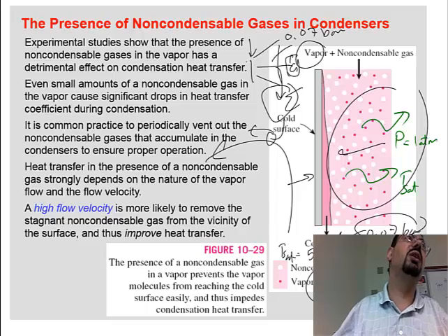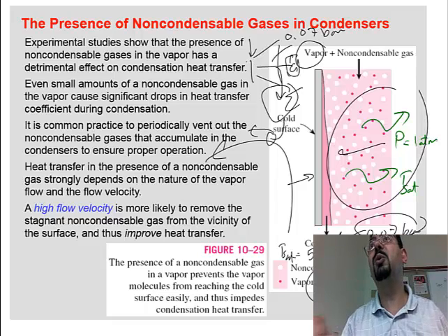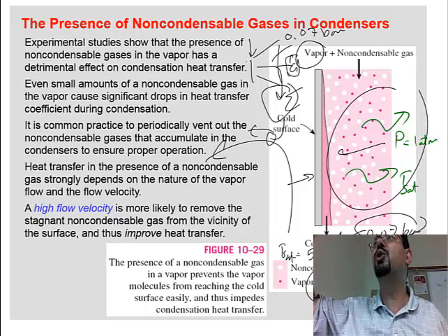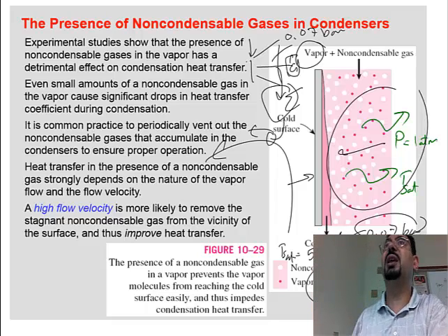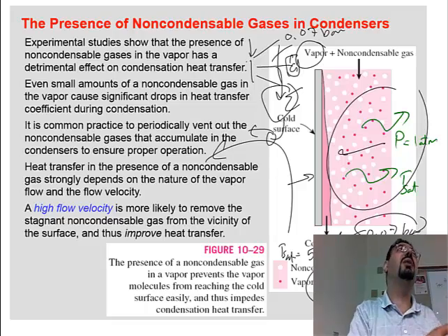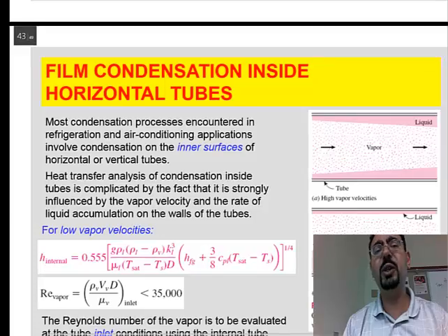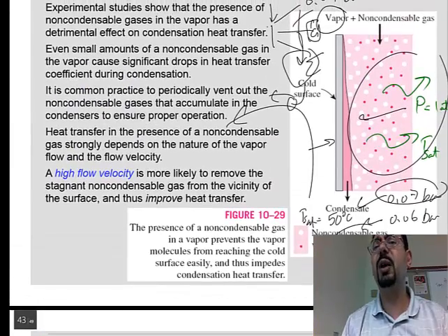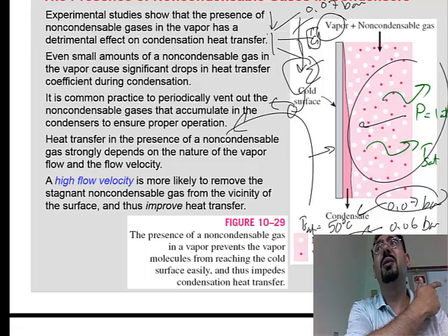How can we do this? It's already hot outside, so there is no chance we can cool it. But maybe drive the water even faster, because remember the water, as it goes through the condenser, its temperature would increase because it's taking Q. So it comes in at 40, it leaves at 45 or 50, right? Anyway, this is why it's bad to have air leaking into the cycle, and you don't want to send it also to the very hot boiler with very expensive pipes. You don't want to have oxygen at that temperature next to those pipes.